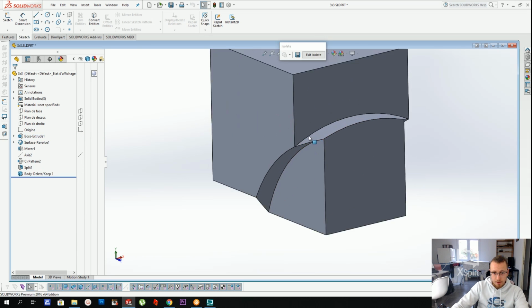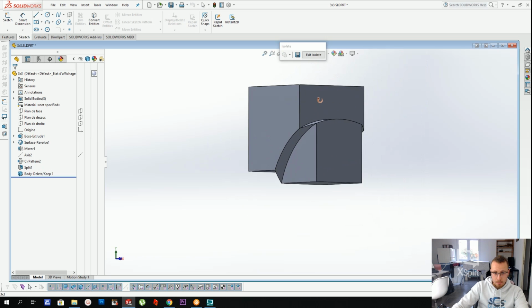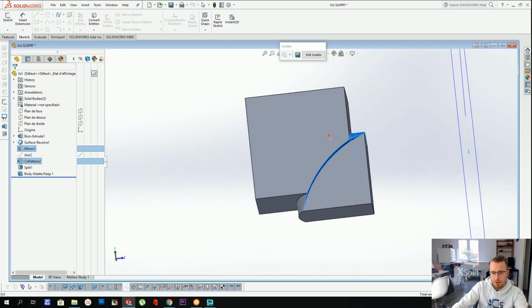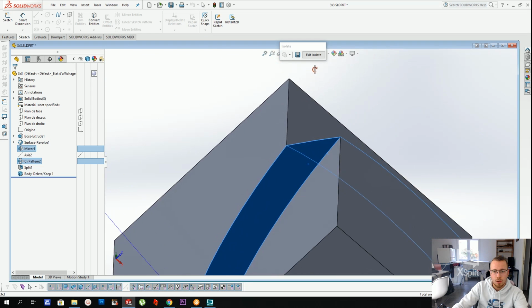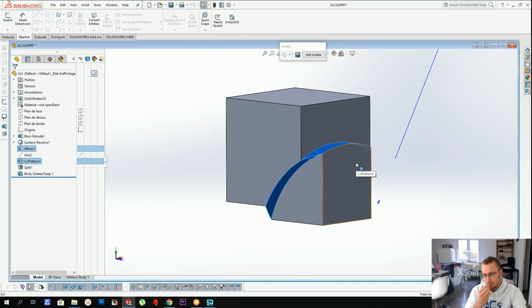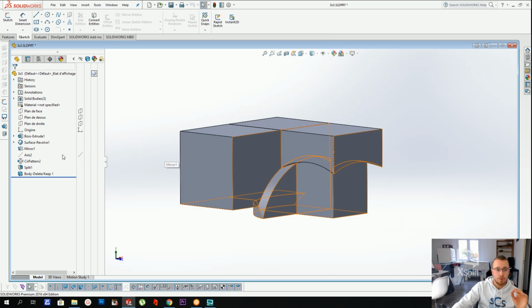But first I want to show you something. You see here on the edge, because of the cylindrical mechanism, the intersection of 2 cylinders is actually a sharp edge, and that's something you want to avoid at all costs on a twisty puzzle, or at least on a 3D printed design, because it makes the whole design complicated, and you cannot go into further complications, such as the shell mechanism, for example. If you want to make more complex puzzles, you need spherical mechanisms, so you have to start with that. And the 3x3 is a great place to start.